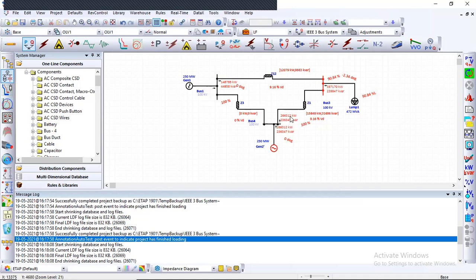So the combination of kilowatt and kVAR is called the apparent power rating, that is kVA, which shows the combination of these two things. After applying the Pythagoras theorem, you can see that the combination of real power and reactive power forms the kVA rating. Both entities at the same time, in the same combination, can represent the apparent rating.